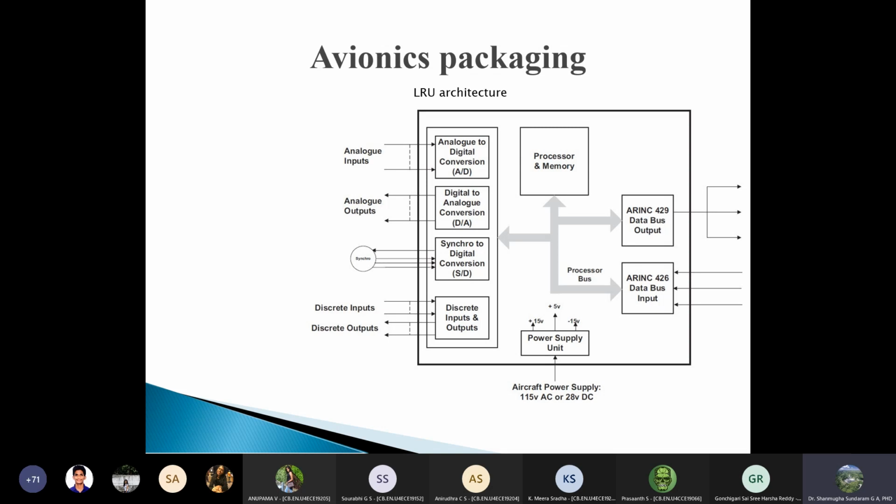From there, there are possibilities to convert it down to something which is a TTL ready scheme, okay, which is the plus minus 5 volts and a 15 volt standard. So that is a scheme of conversion which is utilizable by the electronics, and that in turn is derived from a higher level of voltage that is specified for the aircraft as 115 volts AC and 28 volts DC.